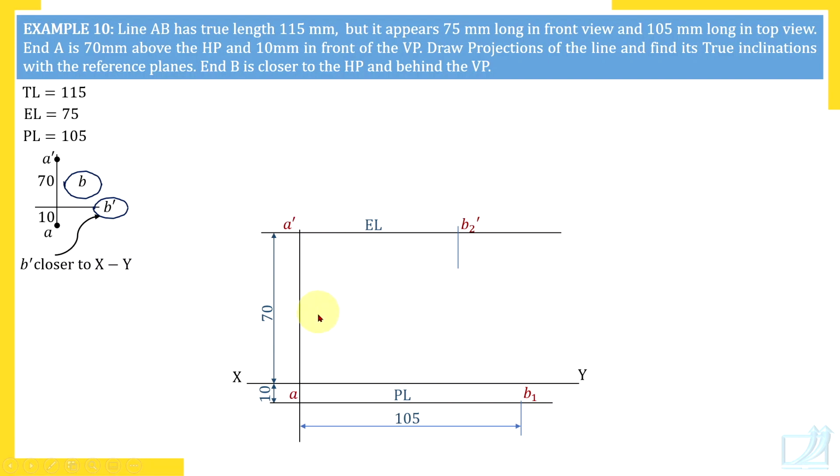So this is how we have brought that information on paper, but still true length we have not measured in our drawing. Which view gives true length? A dash B1 dash, but we don't know that angle theta, and also AB2 gives true length, but we don't know that angle phi, so we cannot draw AB2.